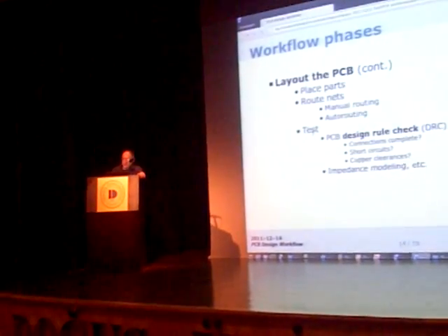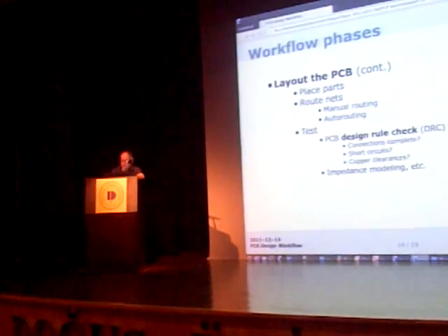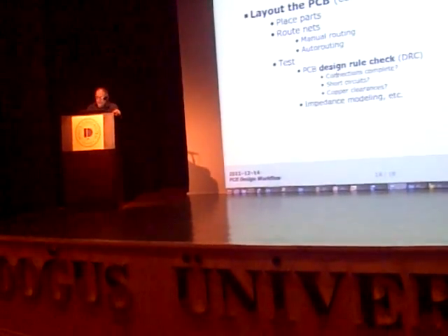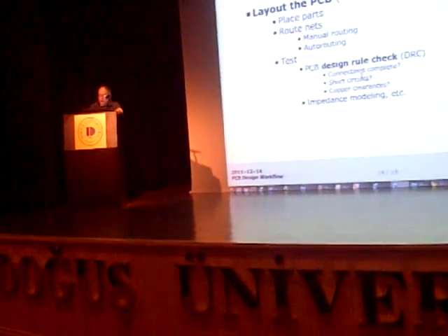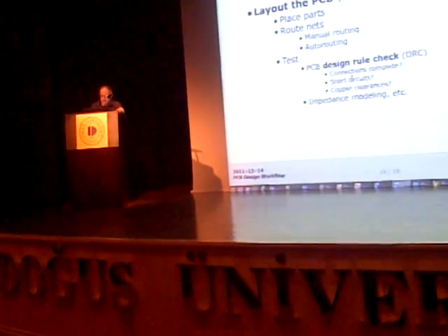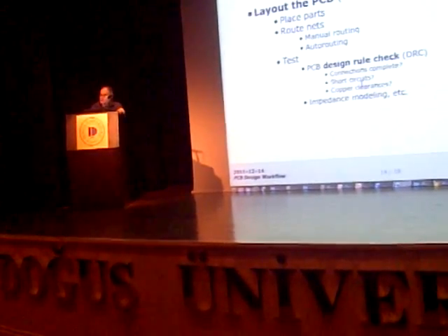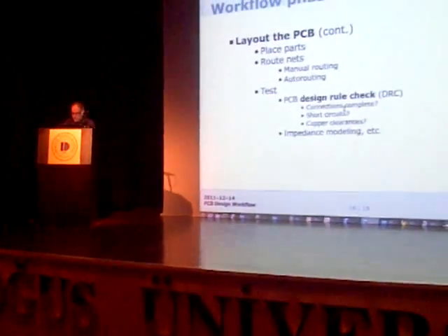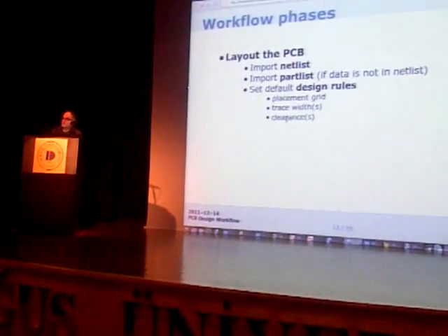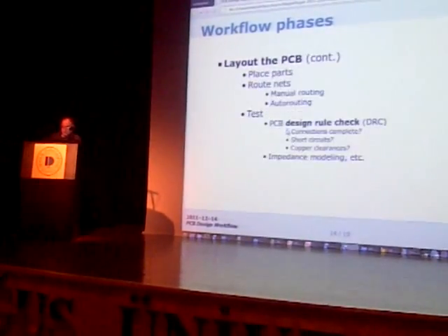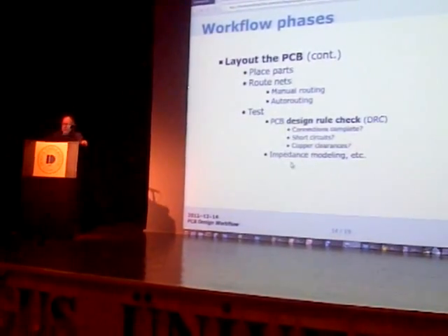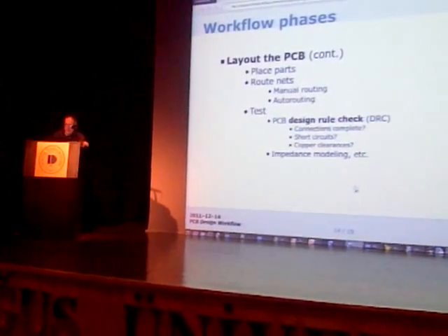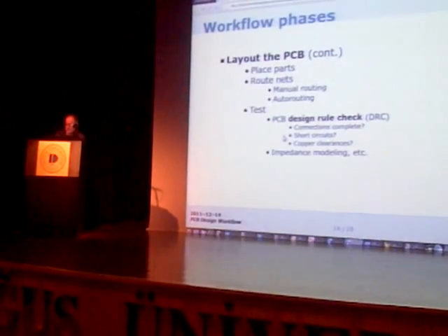Finally, when you're done routing, you do a test using the PC board design rule check. This test phase tells you whether all your connections are complete, whether you've got any shorts, and whether all your clearances are as you specified back here. You can also, in some advanced tools, do things like impedance modeling and some other advanced kinds of tests of the physics of your board.